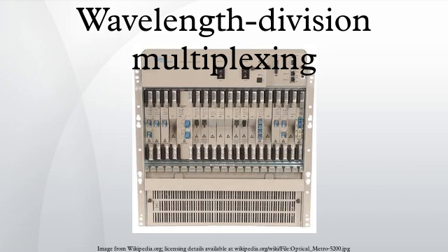networks. The Ethernet LX4 10Gbps physical layer standard is an example of a CWDM system in which four wavelengths near 1310 nm, each carrying a 3.125 gigabit per second data stream, are used to carry 10 Gbps of aggregate data. The main characteristic of the recent ITU CWDM standard is that the signals are not spaced appropriately for amplification by EDFAs. This therefore limits the total CWDM optical span to somewhere near 60 km for a 2.5 Gbps signal, which is suitable for use in metropolitan applications.